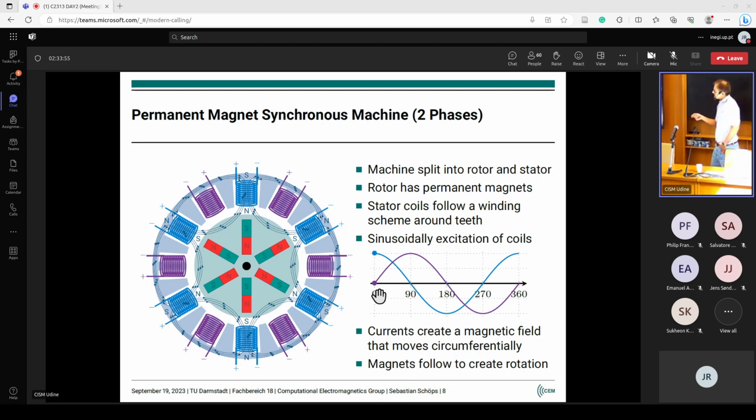So let's say you can completely perceive a quasi-static regime. So I'm not talking about time. I'm talking about angle. So the current is moving between 0 and 360 degrees. And let's say at the beginning, the current in the blue coil has 1 ampere or whatsoever. I don't care about the units here, so it's 1, or whatever unit you prefer. And then this coil creates a magnetic field. There's a north pole over here, and the purple curve is just off, right? It's 0 amperes.